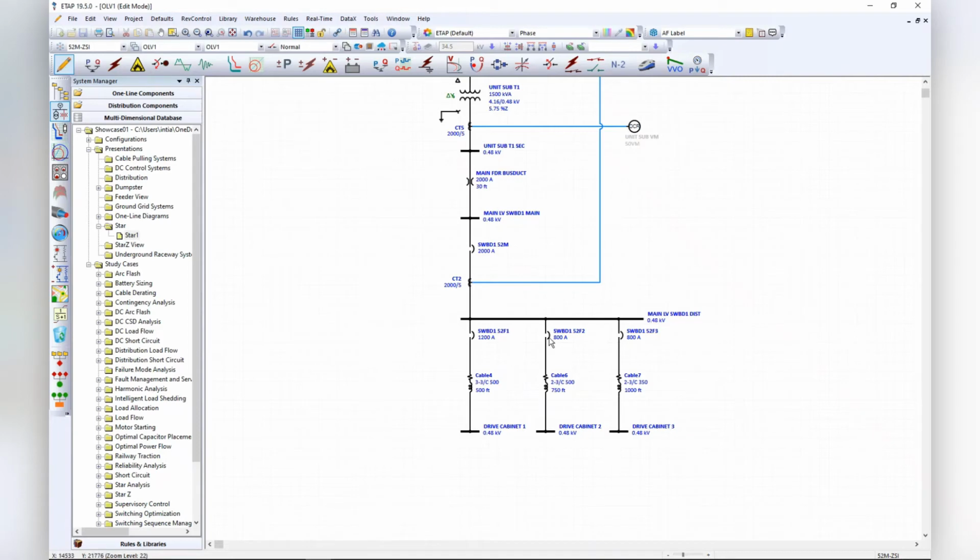When you do this with molded case breakers and power breakers and all that, you need to buy whatever the manufacturer is selling to you, and you need to understand exactly how it's done and how that equipment interacts with each other. So for instance, the Eaton selective interlocking that goes with the 520, that thing doesn't work on instantaneous. That thing only works on the short delay band. So you're going to see it now on the TCC, but it doesn't work with the instantaneous.